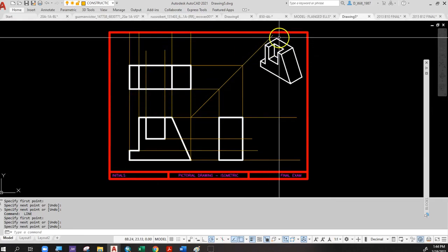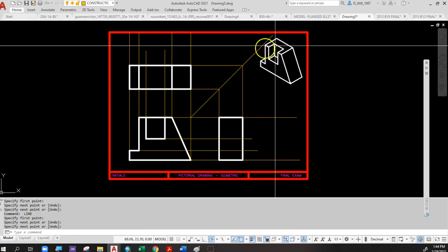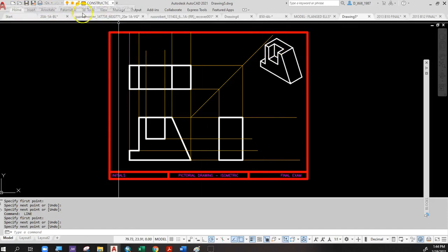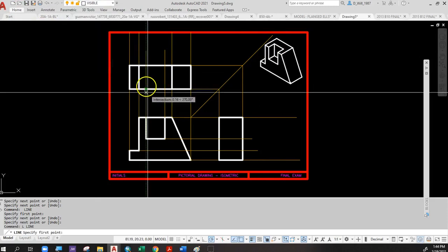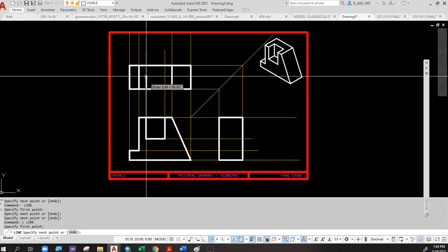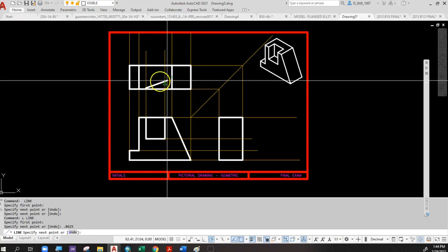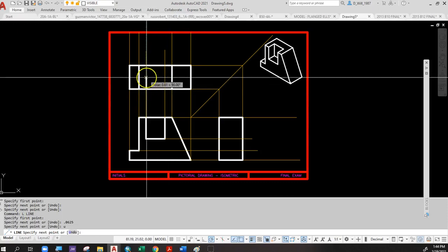So just like I knew the depth of the part, I need to know how deep this is here. And I do know how deep that is. So I'm going to draw that notch up in the top view. And I know where to start. I start right there, right? So it's 0.065. Oh, it's 0.625. That's a little bit different than 0.065, huh?